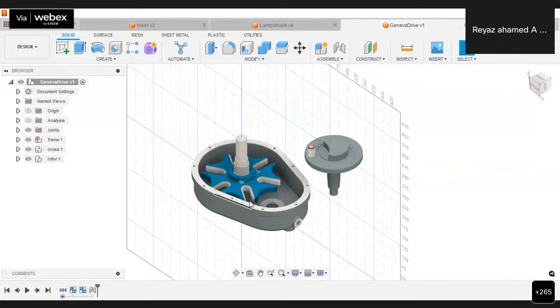I'm going to assemble this component here actually. Okay. So before getting into that particular assembly, I'm going to expand this rotor, and then make the components of the rotor a rigid group. That is, it should not be moved individually. If any part of a component rotates, the total component only may get rotated, and the total component only can be translated. Whatever motion you apply is going to be applied on the total component only. So for that, I'm going to make it a rigid group.